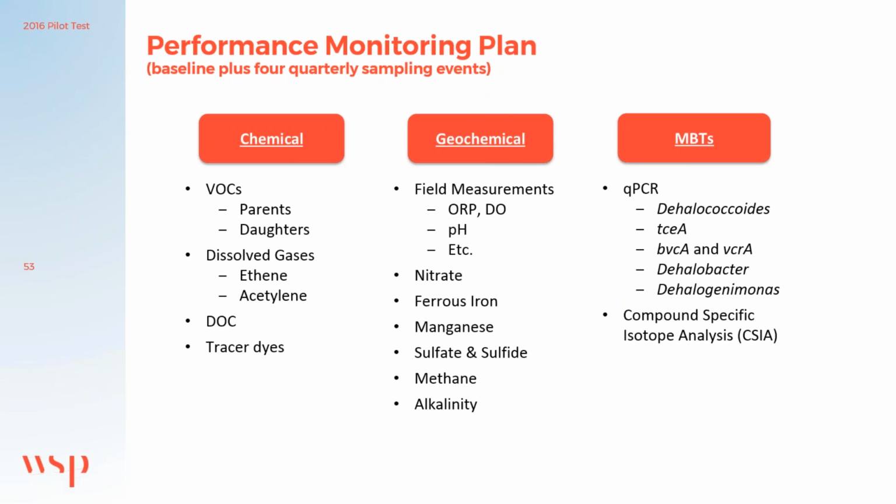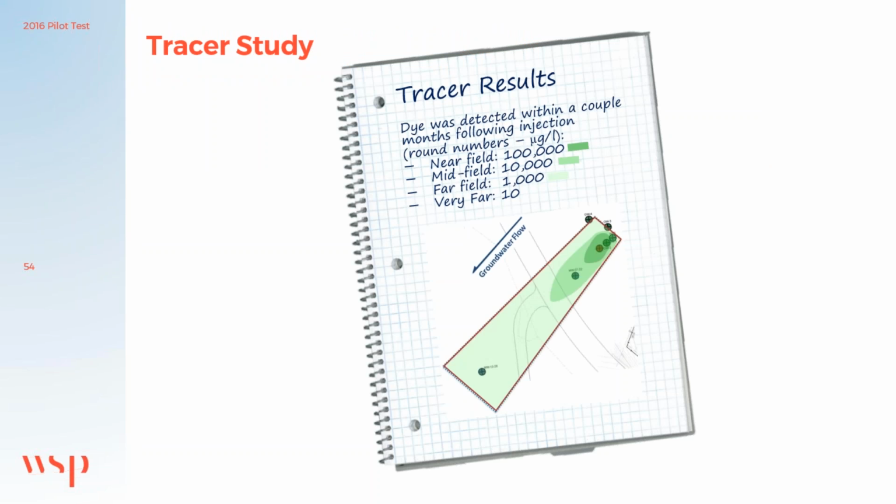Here we see the results of the dye tracer testing. The dyes show great fracture network connectivity. The dye was delivered to the most distant pilot test well, MW13, 320 feet down gradient. Concentrations weren't all that high, but we showed connectivity.